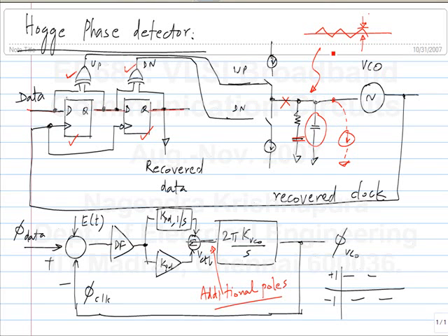So in that case, the actual value is supposed to be here, but then it starts drifting, and you can again see how long it takes for the phase error to accumulate to a certain extent. Okay. So you know the gain of the VCO. So you know the relationship between the control voltage and the VCO output. So from that you can figure out how long it takes for it to drift.